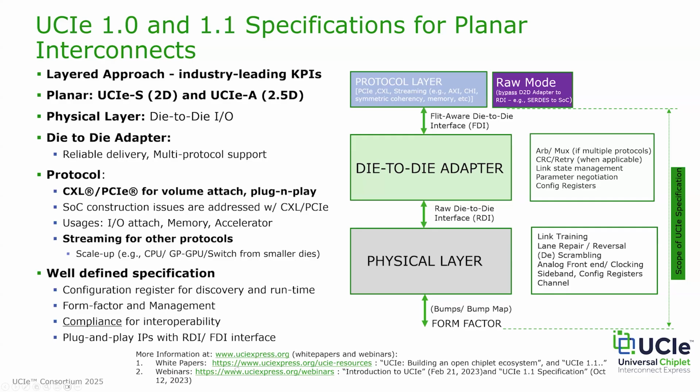On top of the physical layer, you have the die-to-die adapter. It handles reliable delivery of the bits. It has things like CRC, retry, and it can support multiple protocols by dynamically multiplexing between them if that's needed. Protocol layer can be PCI Express, can be CXL, can be any proprietary protocol, can be any streaming protocol.